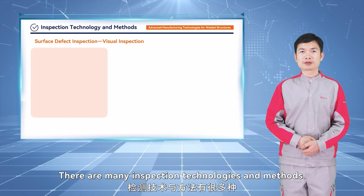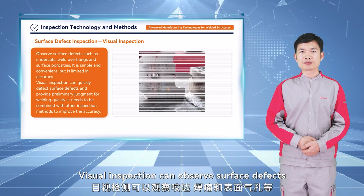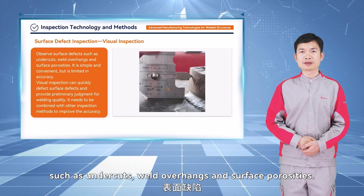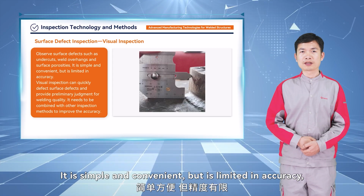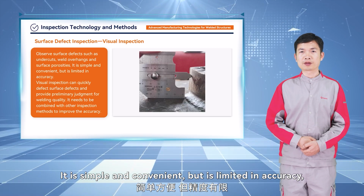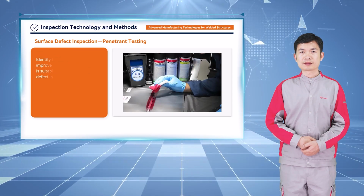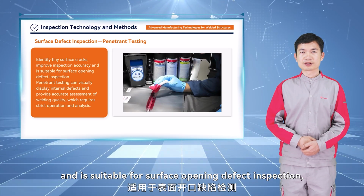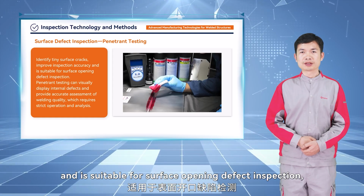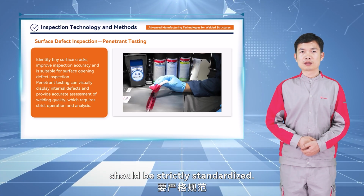There are many inspection technologies and methods. Visual inspection can observe surface defects such as undercuts, weld overhangs and surface porosities. It is simple and convenient, but is limited in accuracy, and it is usually used in combination with other methods. Penetrant testing can identify tiny surface cracks and is suitable for surface opening defect inspection, but the operation and analysis should be strictly standardized.